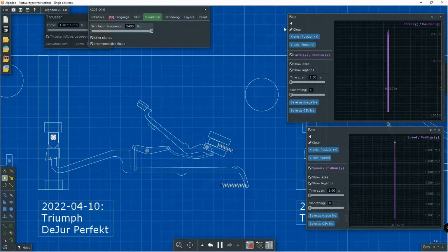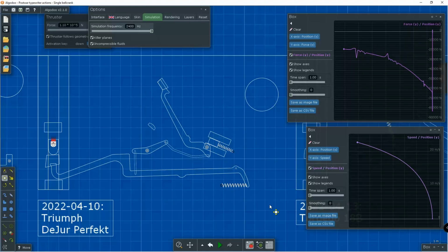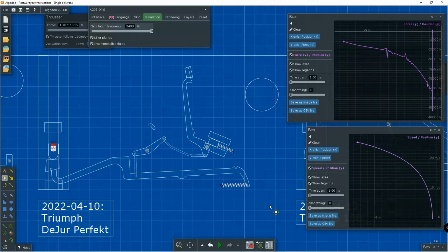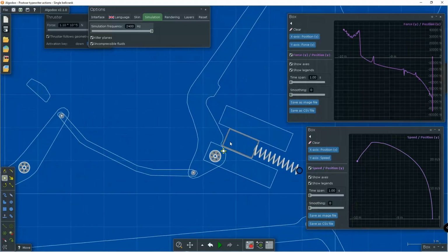Likewise, we have the Triumph-Adler Perfect, or just the general Triumph-Adler portable type action, at least prior to the 70s, and excluding the Adler Privat. And you can see here, it actually initially gets a bit of a decreasingly increasing force. Then we have an inflection point around halfway, then it increases. Yeah, that bump there is from my simulation of the behind segment universal bar.